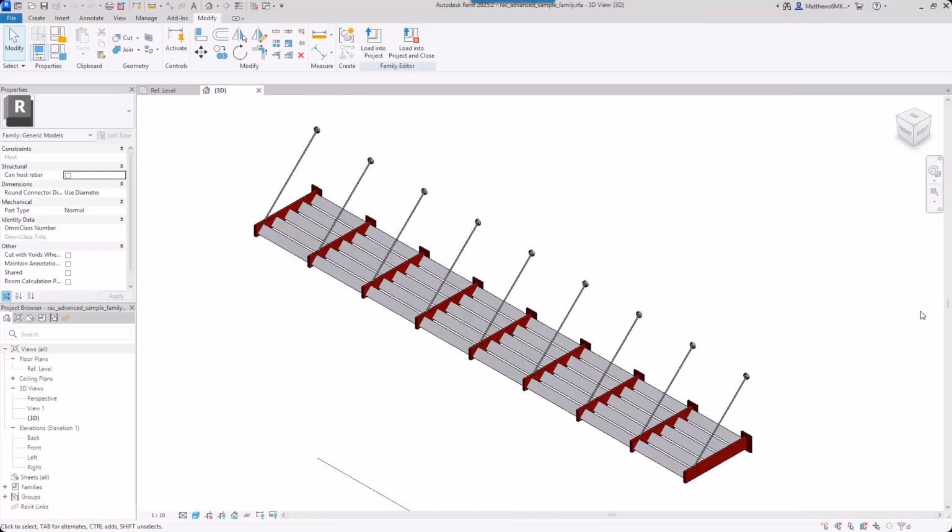And I should note that we're using Revit for this example. I've personally gone through similar exercises using other tools like Tekla. So Tekla 2025 has a very similar export to STEP that will take this information and share it with other formats that might not necessarily read in a native Revit or Tekla file directly, but STEP is going to be a little bit more universal for 3D simulation.